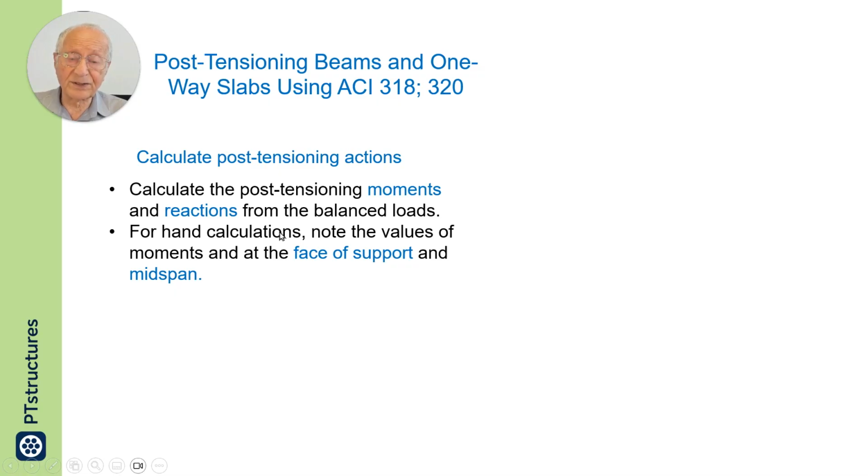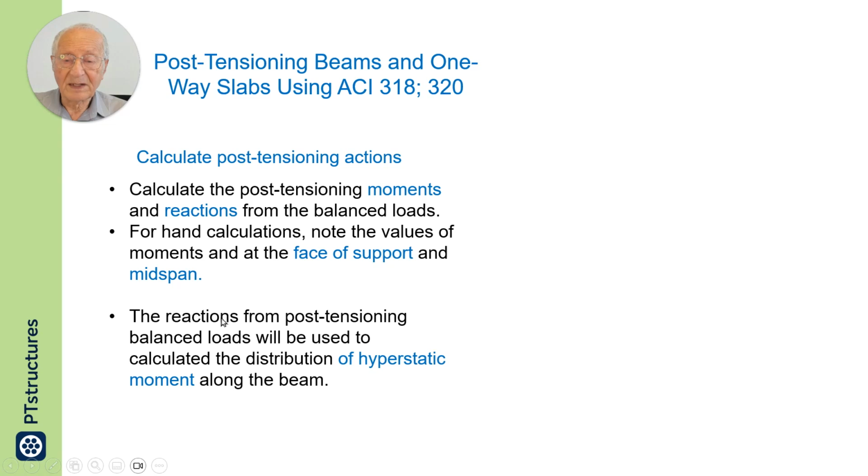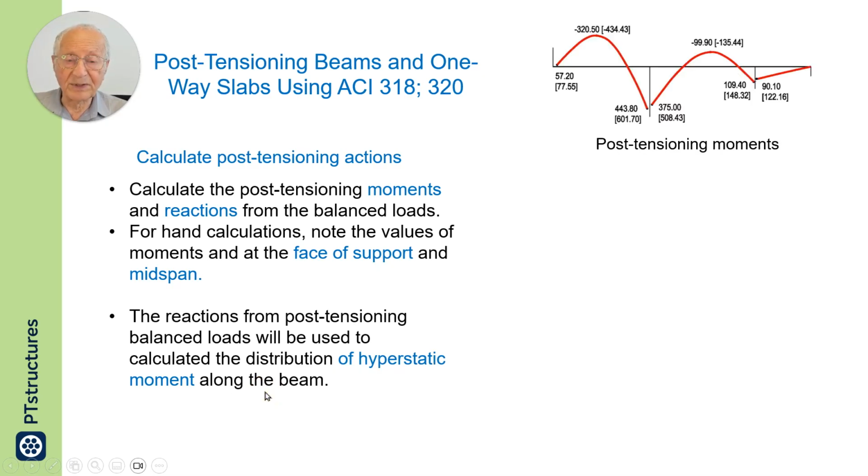For hand calculation, we note the values of the moments at the face of the support and midspan, and the reactions of post-tensioning at the supports. We can note the reactions from post-tensioning for the purpose of later calculating the hyperstatic moments along the member.